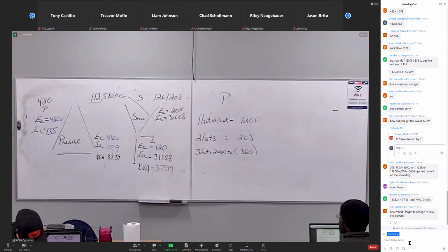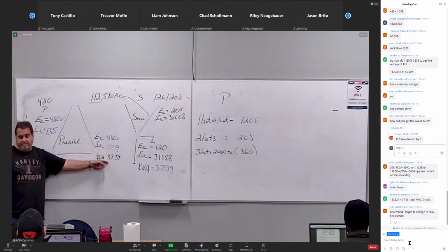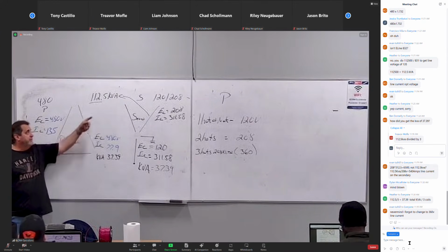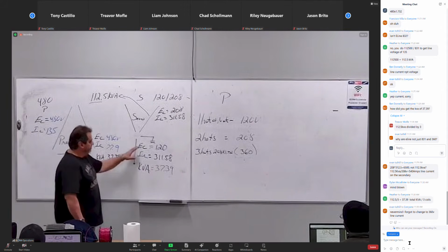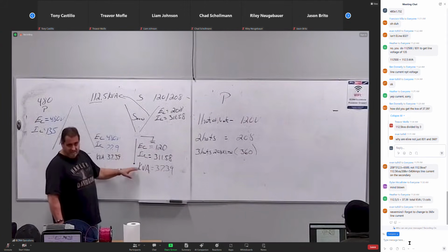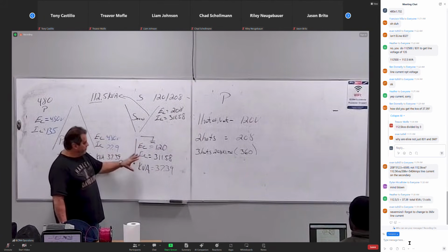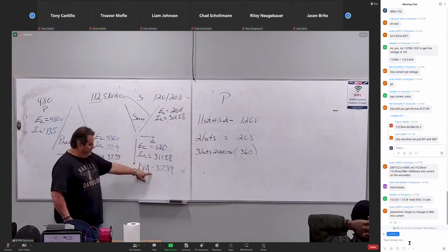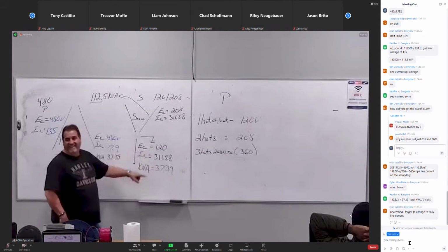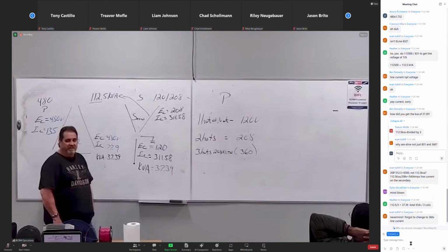Two ways, Ben. One, I could just do my single phase voltage times my single phase current, which is going to give me single phase power. Or I could take my total KVA and divide it by 3. Once you understand the rules, this is Ohm's law. Three-phase transformers are 3 single-phase transformers. Within your coil is Ohm's law. P over IE. That's it. First year stuff. Don't make it any harder than that.